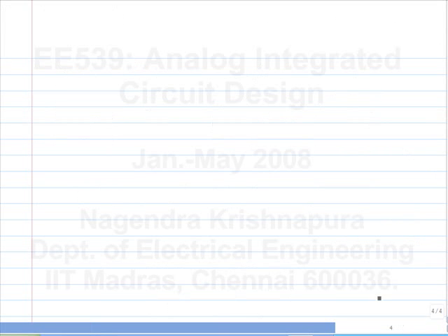Okay, let's evaluate the gain bandwidth product for this. So you have some amplifier with a bandwidth omega u, and from this with proper adjustment of RF and so on, we got a bandwidth of omega u times square root of 2. Okay. So this is the characteristics of the op amp. This is the bandwidth. What is the gain?